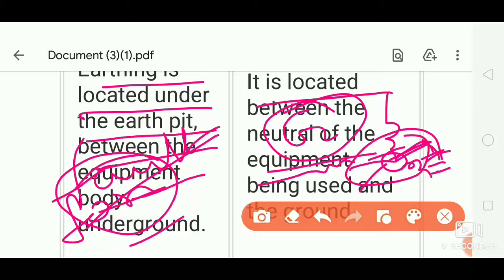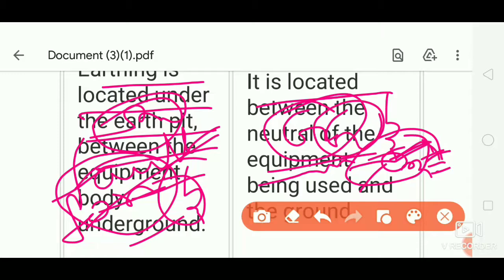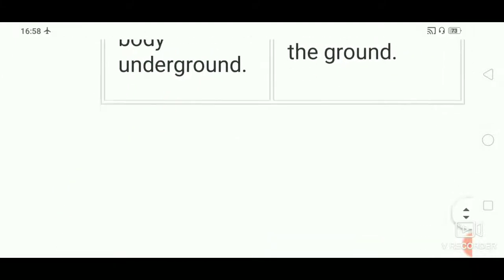This is called grounding. But for household or equipment earthing, there is no current flowing through the system. When a fault occurs, then the current flows through the system. But for the neutral, there is always a certain amount of leakage current flowing through the system. For the solar system, we generally use grounding. So this is another difference between earthing and grounding.